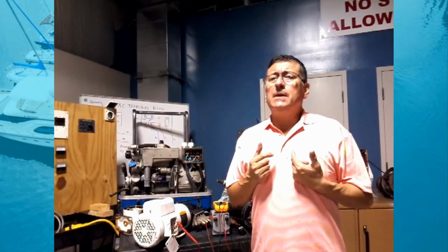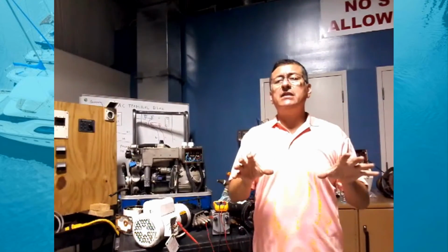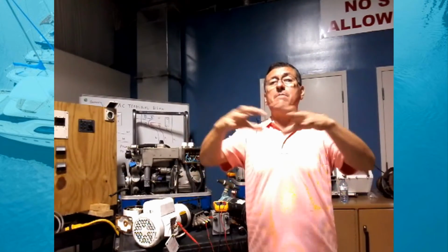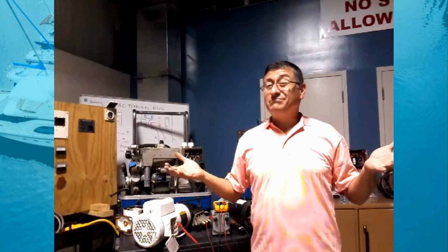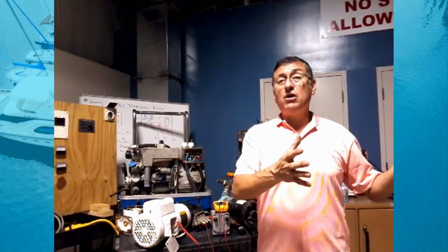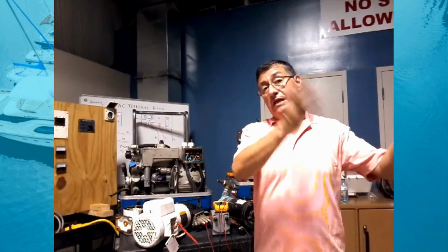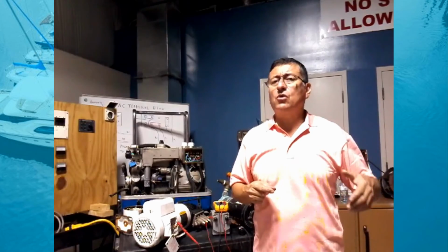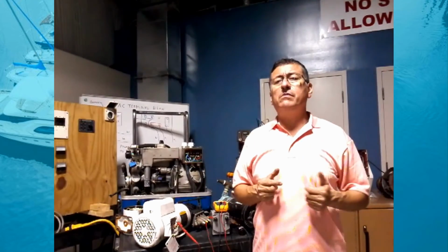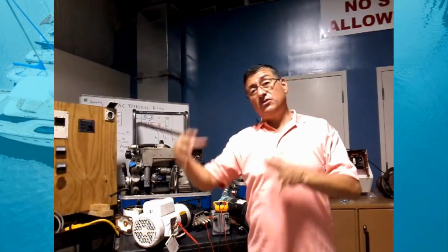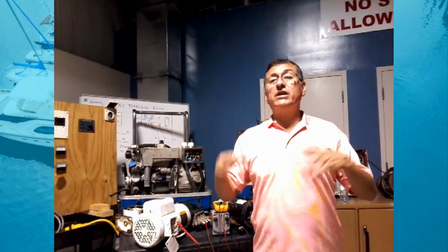But I don't recommend it, because that equipment, the generator, is designed to run engine and generator for some amount of hours. If right now the back end is out, it's an indication that in a couple of months the engine will be broken. Okay, you repair the back end. The back end right now is like a new one, but you have the old engine. Probably in 6 months, the engine is out, it's broken. Low compression, or one piston is broken, or any mechanical problem, and you need to repair the engine. And now, if you add the repair of the back end and the repair of the engine, this is more expensive than replacing the generator with a new one.